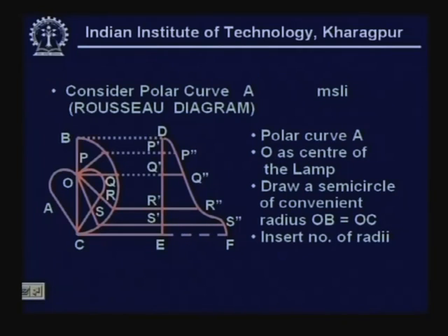This maps, say, at Q prime on the line DE. Q prime, Q double prime gives the luminous intensity corresponding to that angle. So, this is how, supposing you are positioned there, this is the luminous intensity in that direction. So, basically by having a luminaire and a director, you are selectively adjusting the luminous intensity in various directions, whereas in a normal simple source it is the same in all directions.